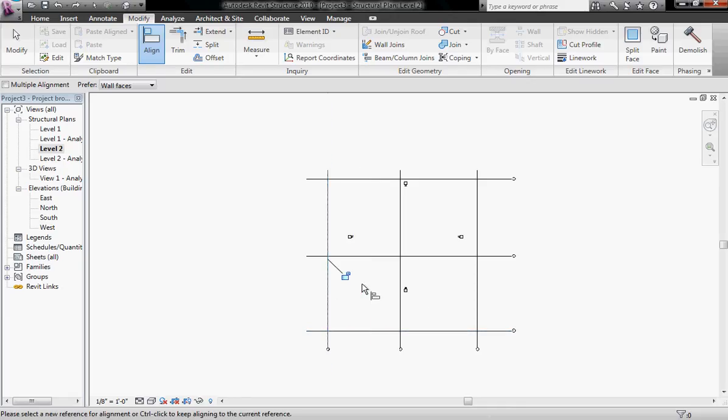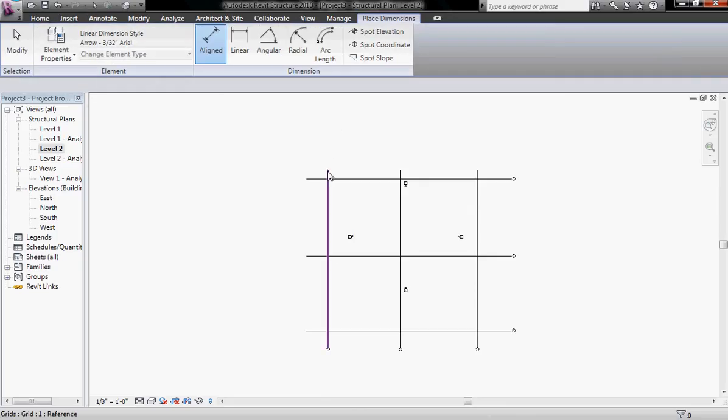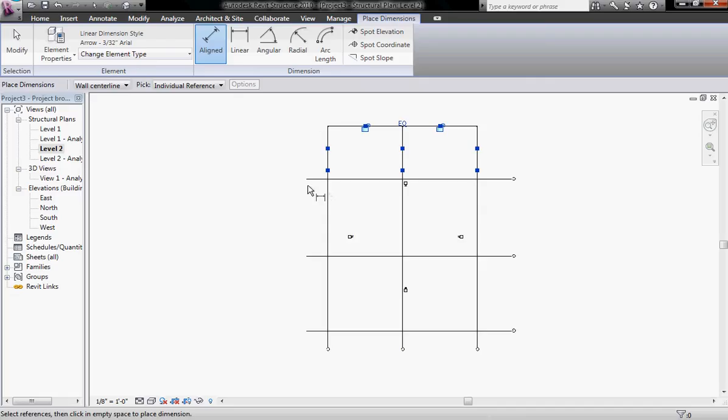Great. So now we have our grid set up, but it doesn't look quite right, so let's annotate it with some aligned dimensions. And what we're going to do is make those equidistant, which is a nice feature, and that'll stay equidistant. That's a constraint that we just set up by hitting that button, and wow, they were actually pretty close. So now we have our grid set up.